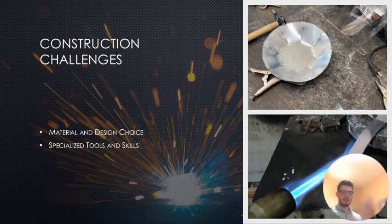And as I mentioned earlier in the design considerations, in order to make it out of sheet metal, I would have needed to use a jeweler's sandbag, a torch, and a small wooden mallet in order to stretch the metal into a parabolic shape, and that also could cause inconsistencies. So it's something that needs to be investigated further to determine if there are better methods for creating this, whether it be personal or commercial.